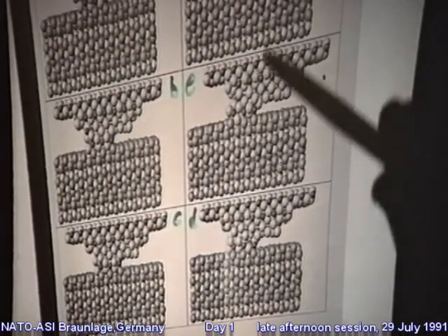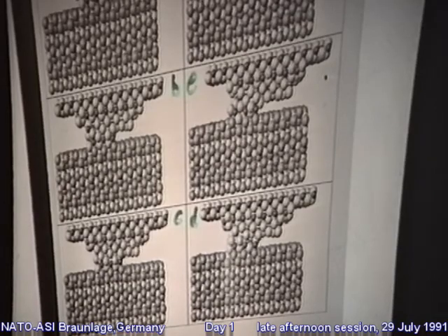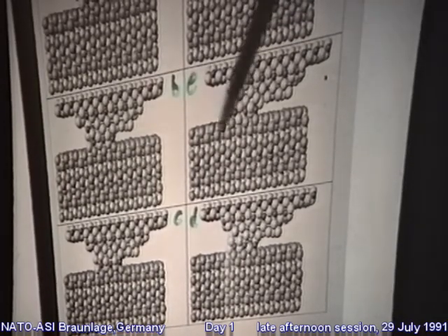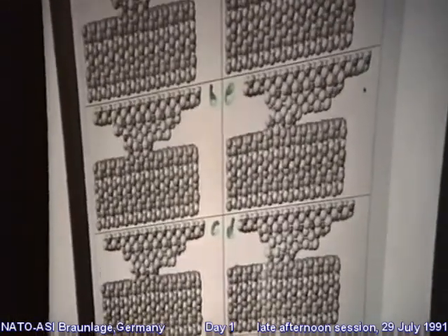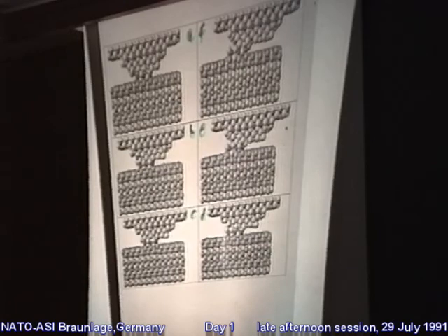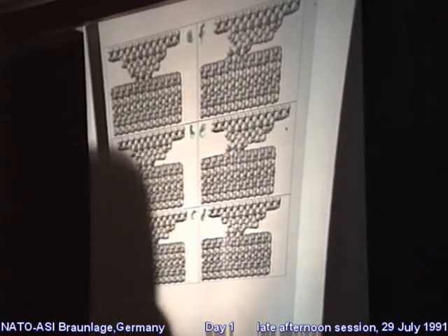And now if you follow this to the end, you see that this part remains stuck to the surface, so you actually get a decent wear particle made of 3 layers: 2 layers of fluorine, and in the middle, calcium plus 2 fluorine layers. So that's the stick-slip phenomenon, the motion of one atom at a time.